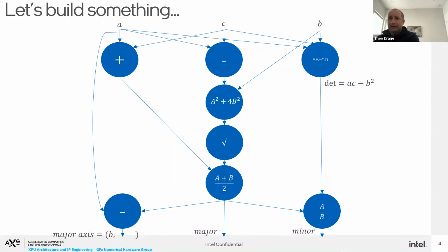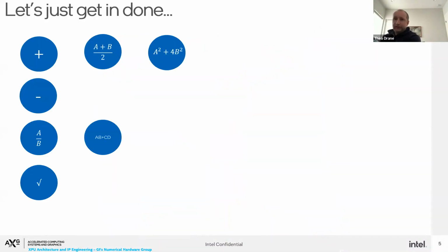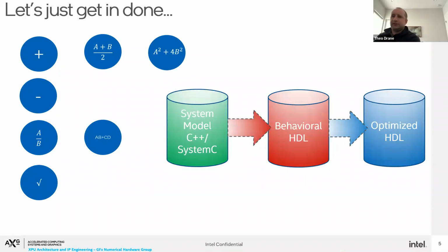One of the many wonderful things of GPU design is that we actually have over 250 different number formats. If we even take this design, we expect the inputs are floating point and the output is actually fixed point. The internal formats are entirely up to us. This leads to the question of needing to build these components, but we have countless choices buried in here as well. Obviously we need floating point adders, we might need dot products. Do we actually build division, or do we just do reciprocal? You have all of these different questions.